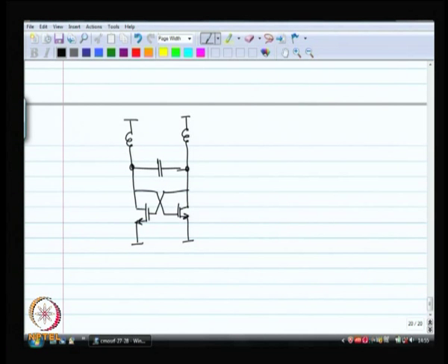If you look at the DC picture, this voltage is at VDD, okay, which means you have got just one NMOS as a diode between VDD and ground. So, it is going to sink a lot of current. You do not really like that.